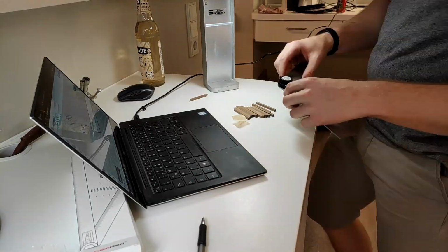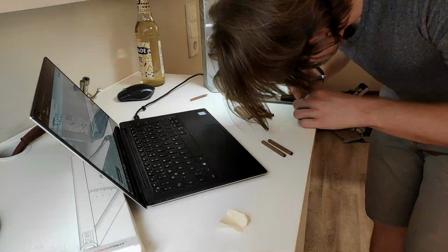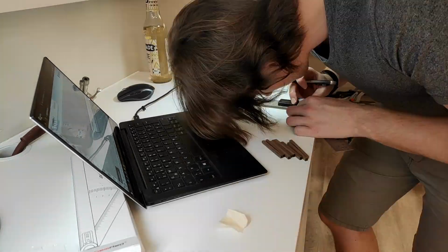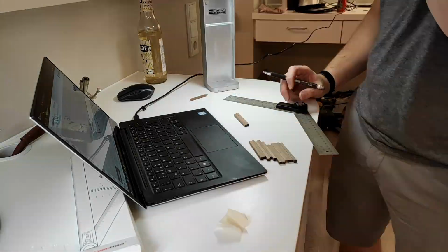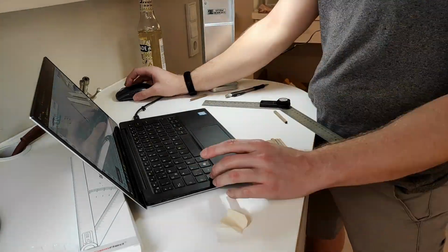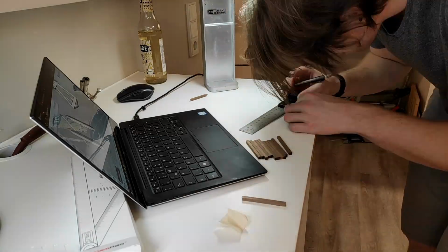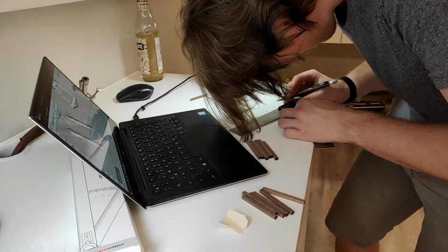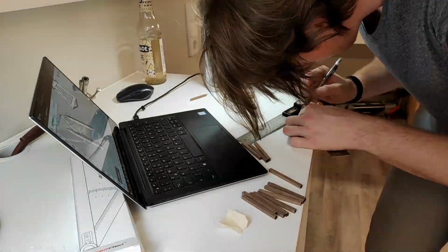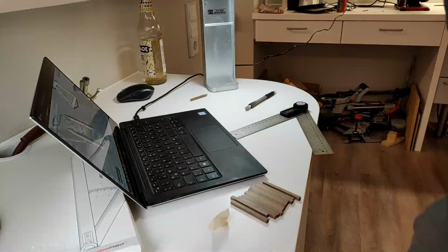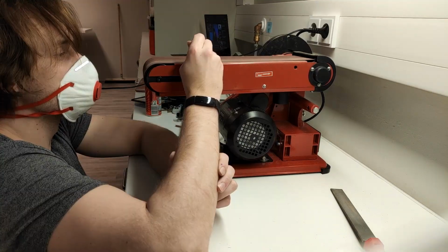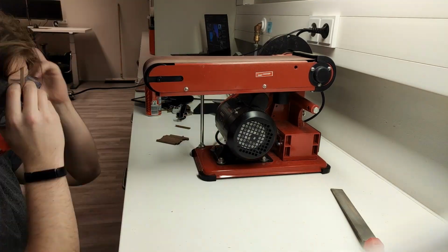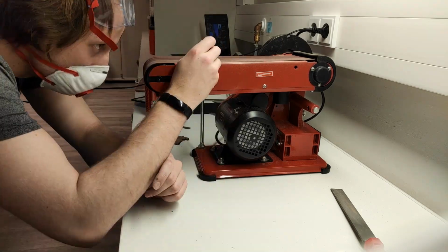After cutting all of the pieces into the desired length, I used an electronic angle measurement tool in order to draw the correct angles I needed to cut into the wood on each of those edge pieces. With the other models I used a bit of a different technique, which I will explain when we come to that. One of the biggest questions I had in mind the whole time when I was thinking about the model was how would I be able to cut such precise angles into the wood, because I knew from previous projects that using something like a miter saw sometimes is just not accurate enough.